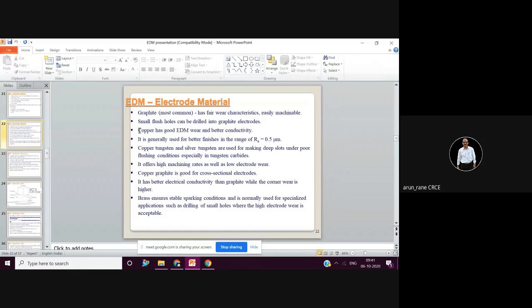Similarly, you can have electrodes for different workpieces. Generally, on an EDM machine, the tool magazine provision is not as high as CNC milling, where we have seen 60 tools, 80 tools, 120 tools, and 180 tools. Normally, EDM machines have maximum 20, and in general, 10 pockets are sufficient.